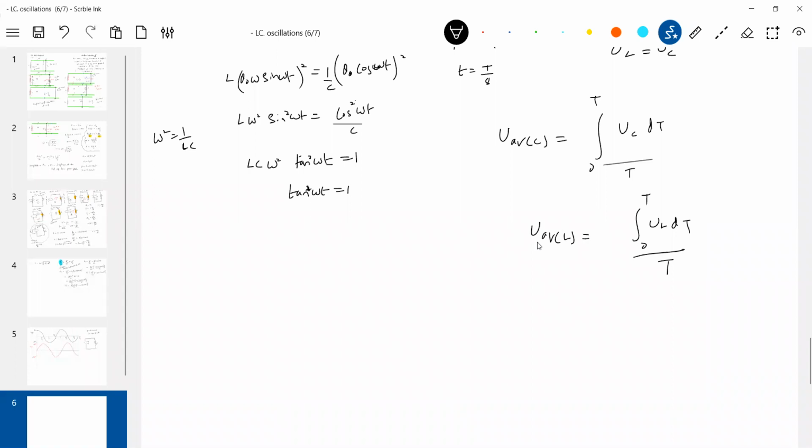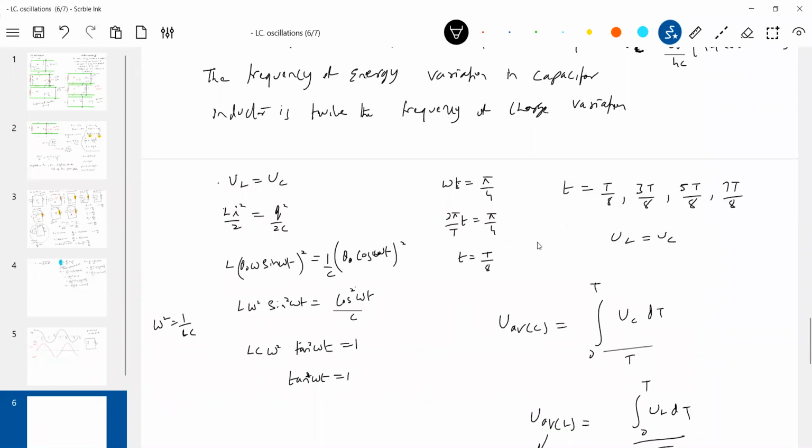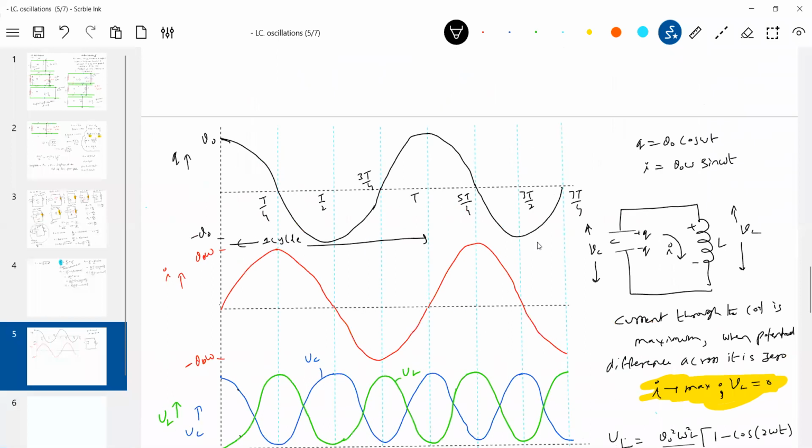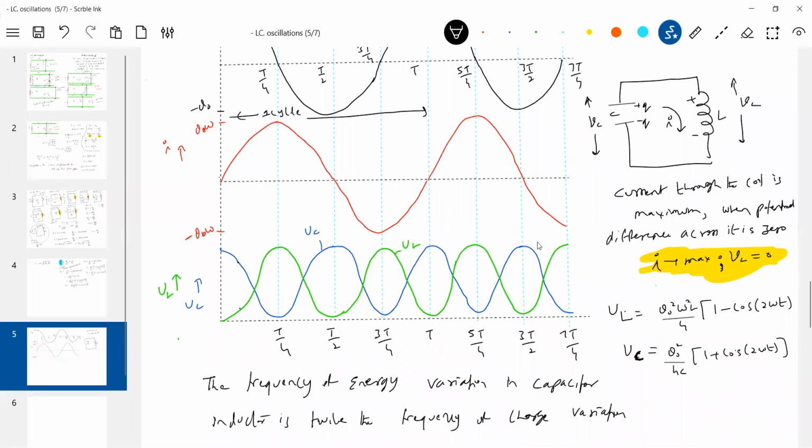You can manage because they give information like what the average energy is. They'll give this as information, and based on this, a problem will be linked for you. What is the average charge flown? Again, go back to the same idea. Average charge should be zero, no? Because there is a negative half cycle. Average current should be zero, since positive and negative half cycles are there. Average energy will not be zero, because there is no negative half cycle.